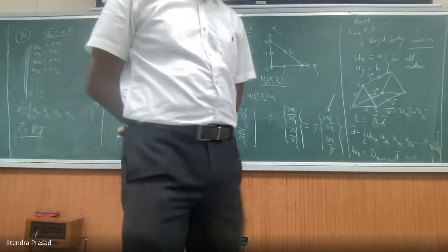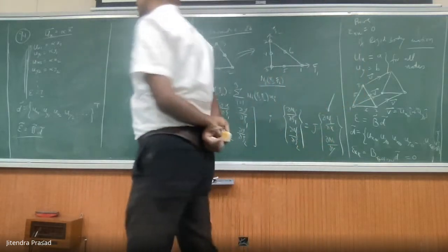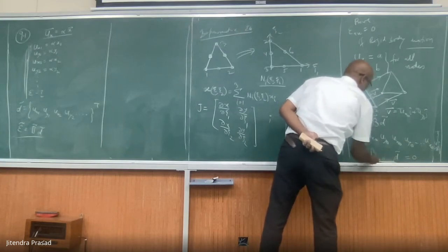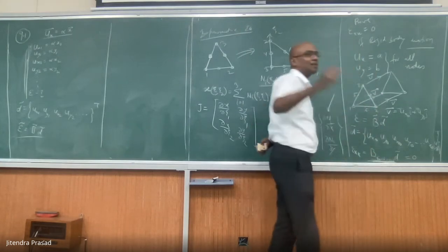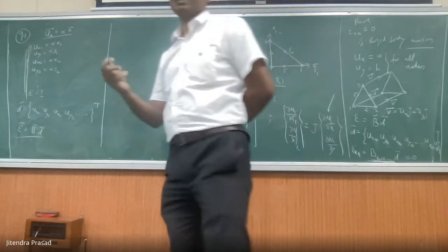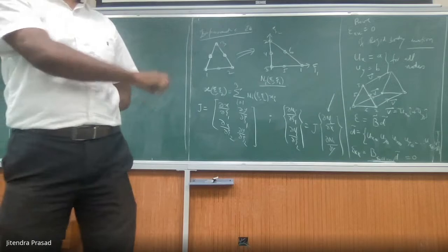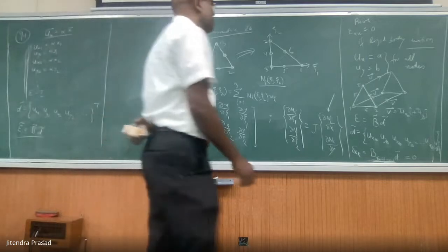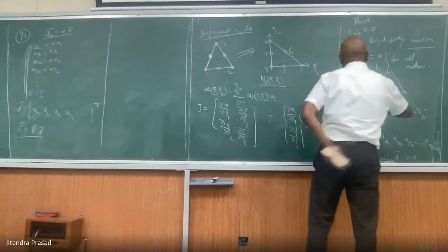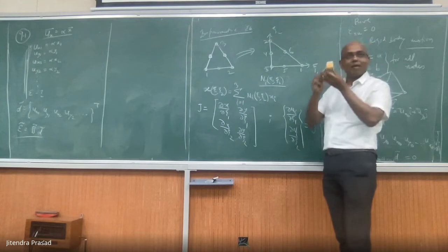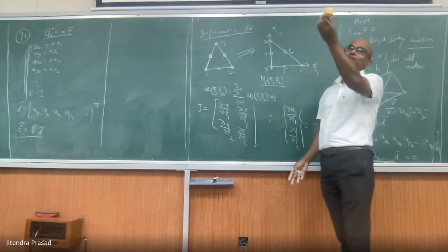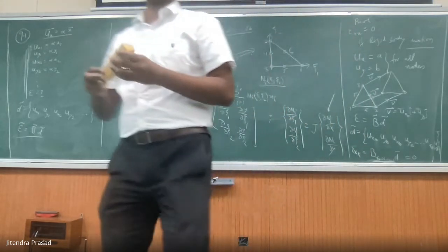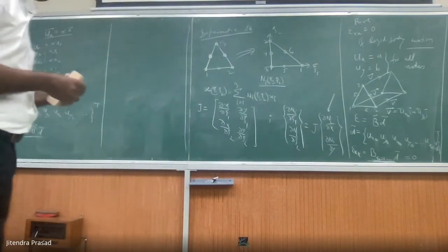Yeah, that will be enough for me. You will get 0. If you calculate the first row and multiply by D, you will get 0. It is just predicted; I did not calculate and write it. I predicted it will be 0. It has to be 0 because rigid body movement means all of them have moved the same, so there is no strain in that case. We just move from here to here. The strain is 0, it has to be 0, and numerically you will get 0.